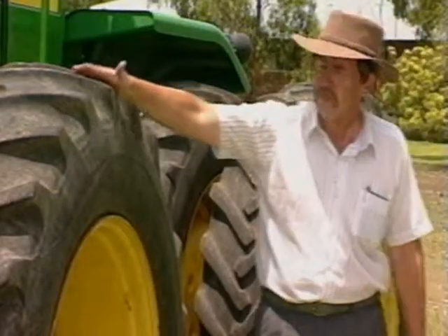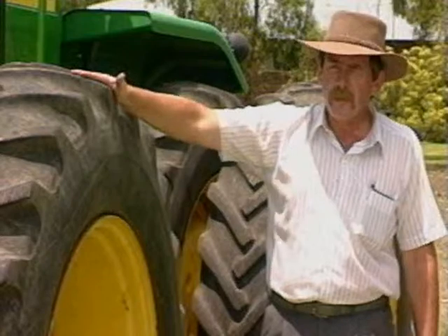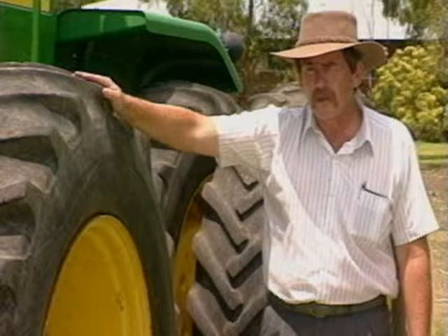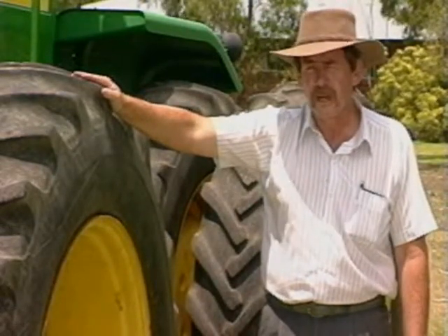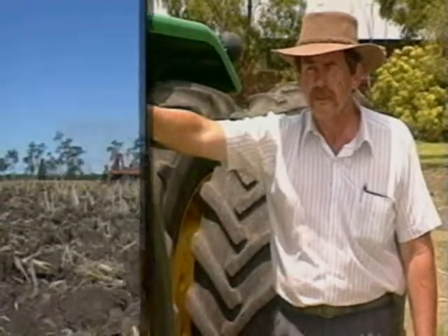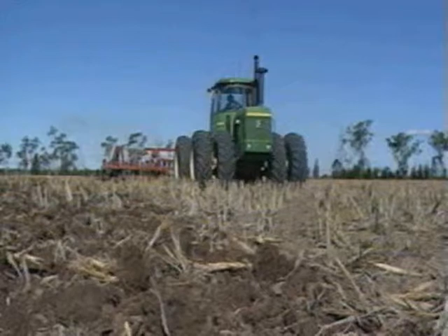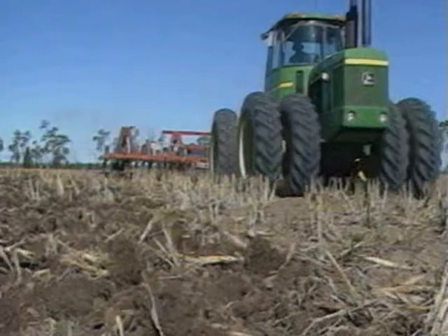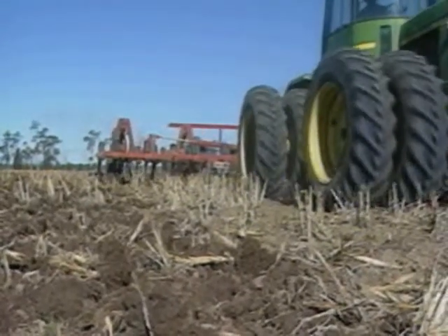Tyre sizing, tyre dimension. Once again, we've seen a tendency to move to higher and higher diameter tyres, and the higher the diameter tyre, the greater traction is gained out of this tyre. The reason being is the footprint is long and narrow and generates a high amount of traction. Other benefits of tall tyres is the lower rolling resistance, and if we have a look at the diagram, we can see why. The angle that the tyre comes out of the ground at is less than a small diameter tyre, hence the reduction in rolling resistance.